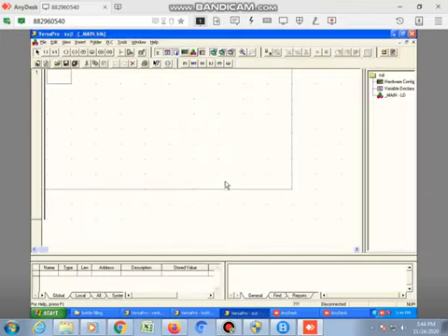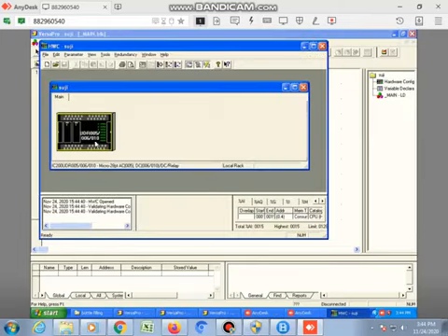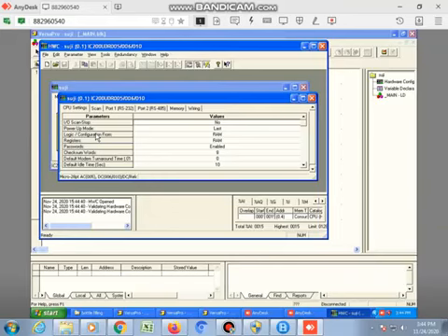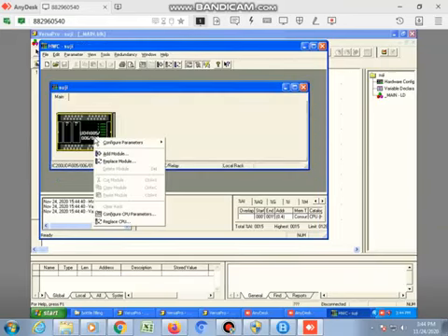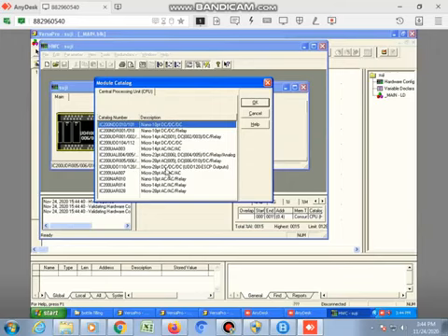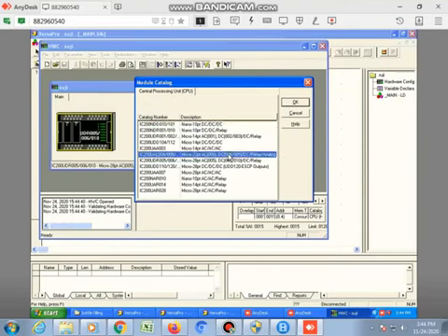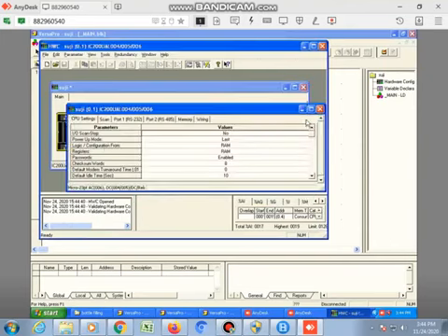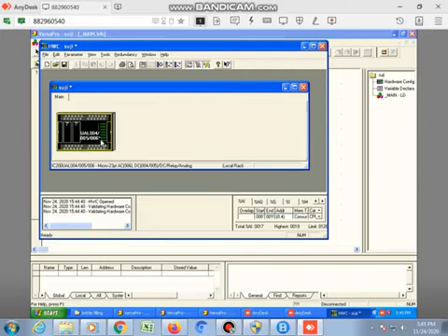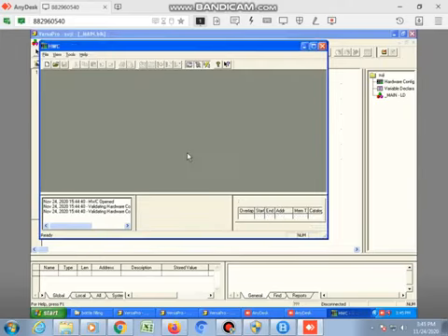So this programming window will come. So we have the contacts. We can take the contacts and place coils, the same as we did for the earlier systems. In this we are choosing the hardware configuration. This hardware configuration we are using is a different hardware configuration, so we can replace our module. This is the CPU we are using, the fourth CPU, so we will be using the fourth CPU. That CPU we need to install instead of 4, 5, 6. So this is one update we have to do.